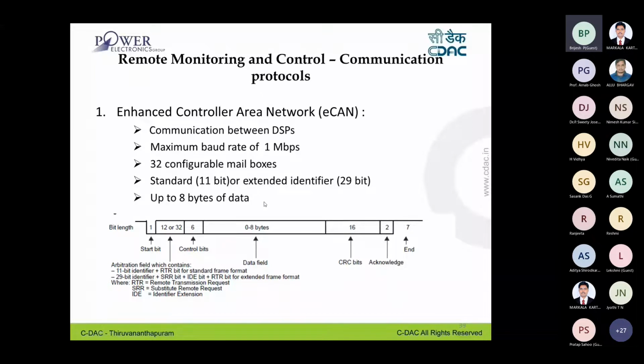For providing the current command or power sharing, you can best use the CAN modules. It will work in a harsh environment. So this is one of the basic communication interfaces used in such applications. You can go up to a maximum baud rate of 1 Mbps within a 40-meter distance.